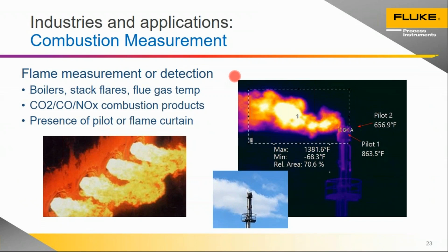All right, and there are applications, and Adam referred to this as well, where we're directly measuring the temperature of a flame. And in fact, what we're doing when we're measuring a combustion or flame temperature, we're really measuring gas temperatures. And so we have sensors that are using wavelengths that are focused on picking up the temperature of common combustion gases. So CO2, carbon monoxide, and NOx. These would generally be filtered to operate and measure a temperature somewhere between 4 and 5 microns, specific narrow bands in there that pick up those gases in particular.